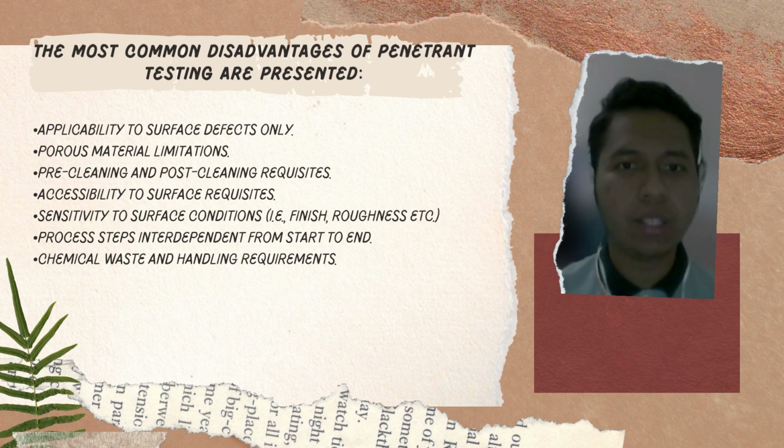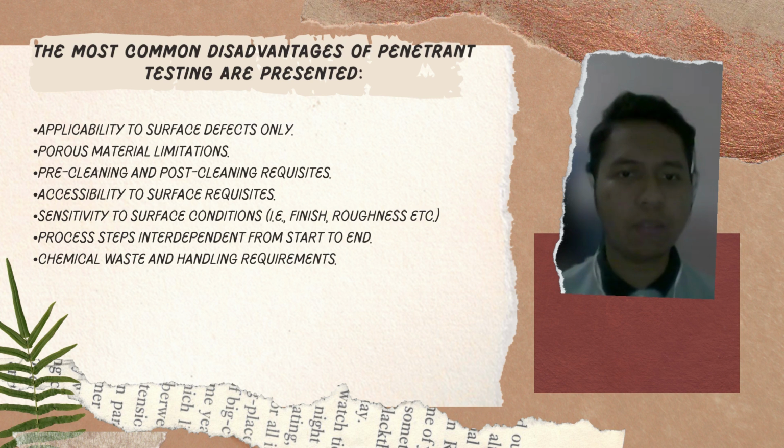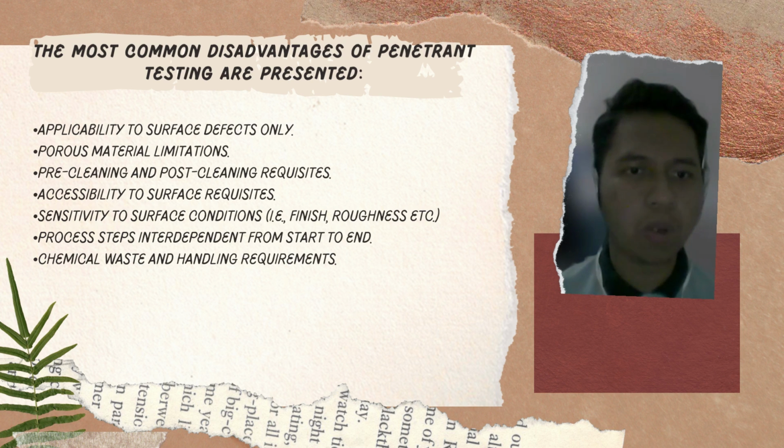The most common disadvantages of penetrant testing are presented. First, applicability to surface defects only. Second, porous material limitation. Third, pre-cleaning and post-cleaning required. Fourth, accessibility to the surface required.